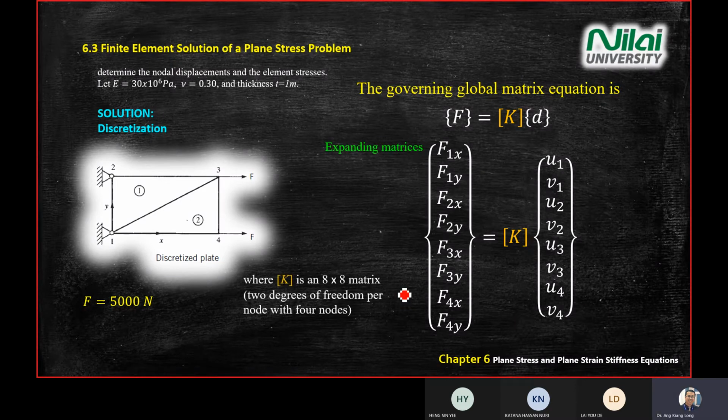Okay. All right, so your K from these slides, you know that your K is 8 times 8 matrix. It's a very big matrix, yeah. So it's 8 times 8. However, after you applying the boundary condition in this diagram, you see that point 1 and point 2 not able to move. It's a pin. It's not able to move. So you can cancel, not cancel, but you can close the matrix according to the boundary condition. Point 1, you close 2 value there.